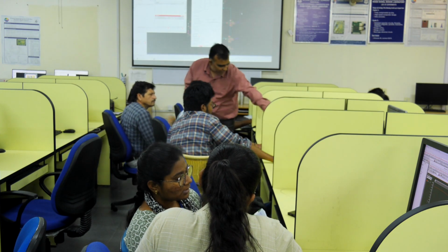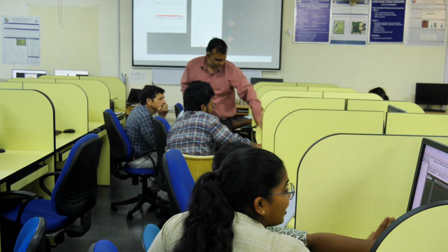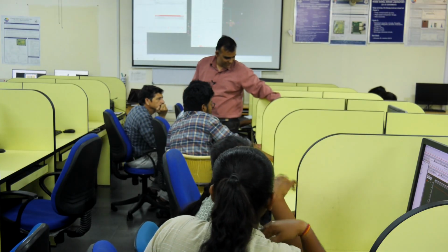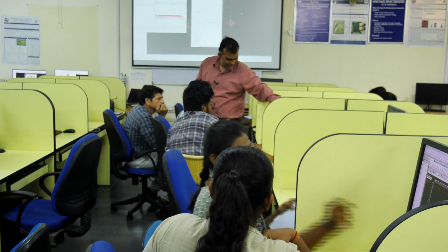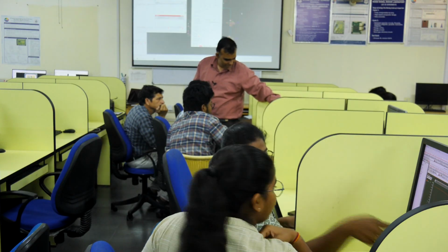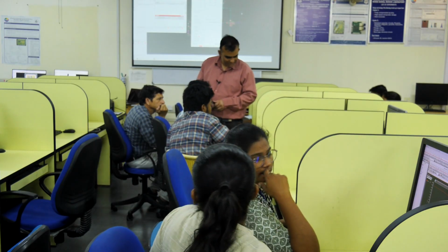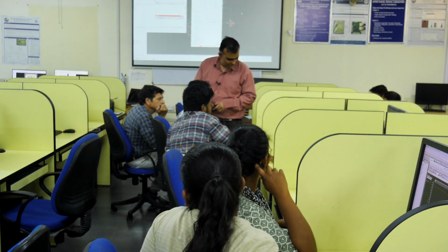And now you want to view the results of the run? Go. So there are already 3 errors which it is saying. Your minimum metal 1 area has to be this much. Minimum diffusion to contacts. You only have 3 errors. That's impressive. But now we need to go and fix these errors, right?